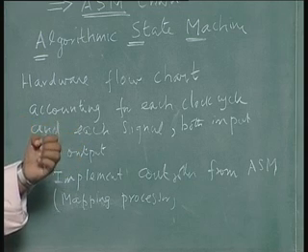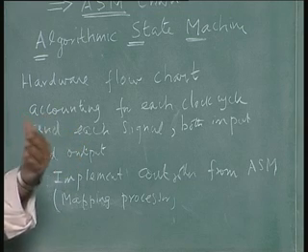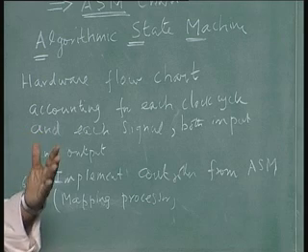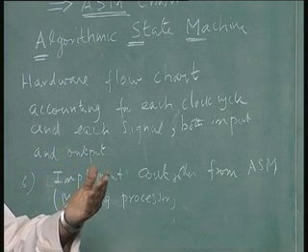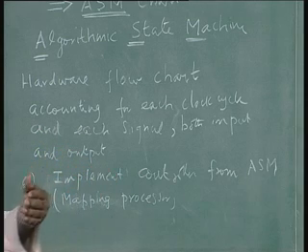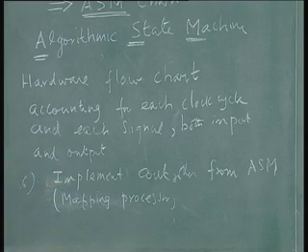As you go in the state graph, even though hardware design is possible, once you have a state graph you have a standard technique by which you can design the hardware in terms of gates or multiplexers or ROM, PLA, all is understood, PAL.